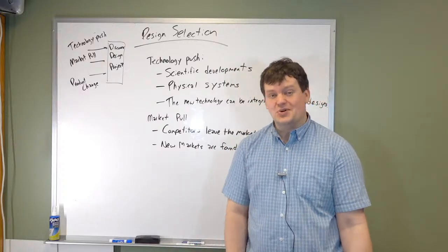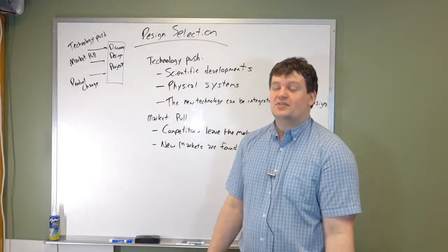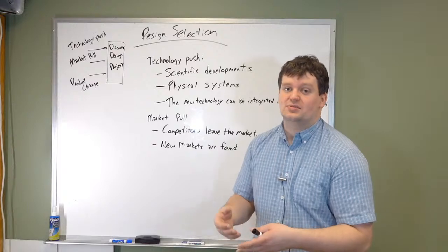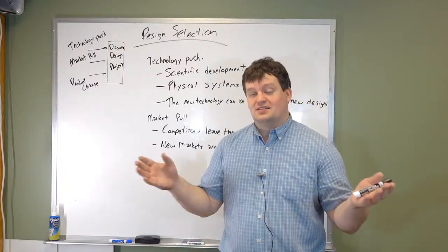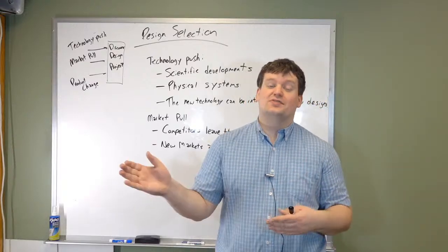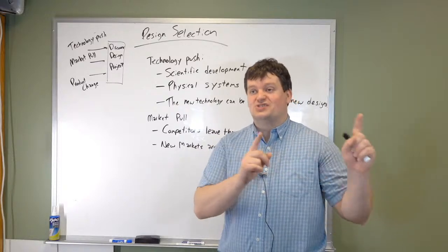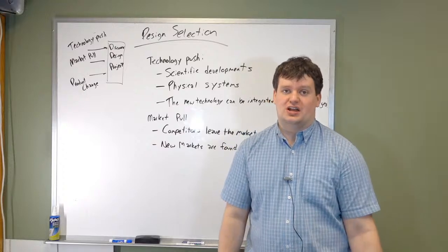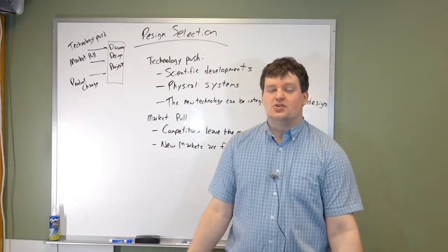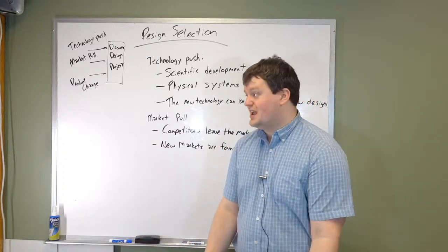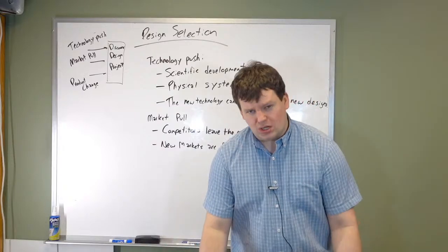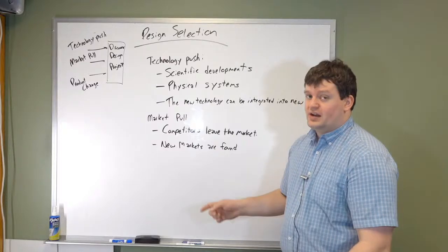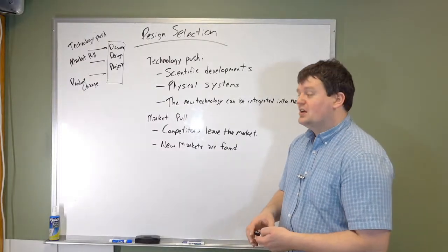Automation kills people too, unless you do it safely, which is where cobots come into existence. Cobots have the ability to sense their environment, sense if they're actually near people, sense if they're impacting people, and then stop. They will actually shut down operation entirely. And that's the beauty of these cobots. So when cobots first hit and you say, hey, we have a robot that won't murder you when you climb in there, there was a new market for it, and it was beautiful.